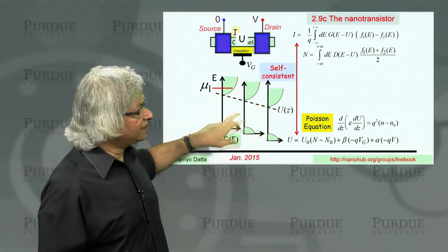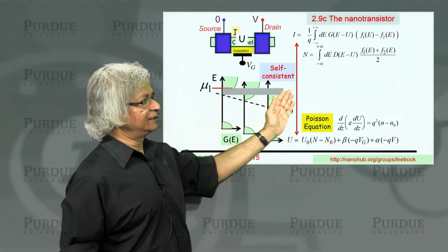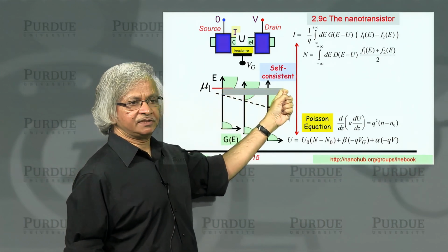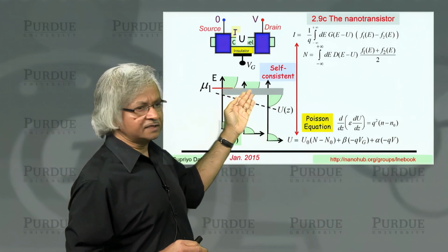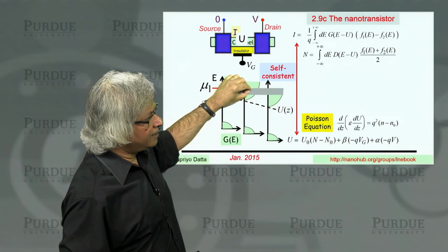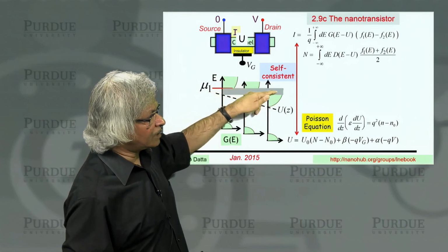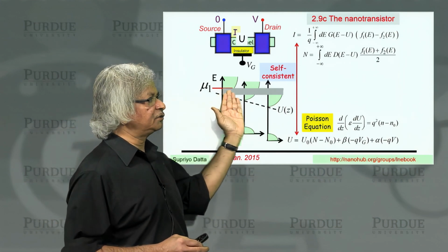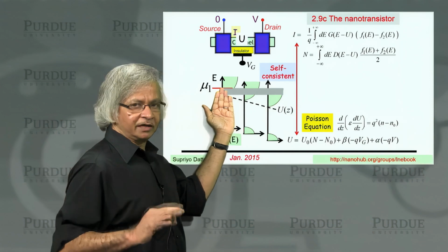Okay? Now, one thing that it misses here also is that, remember, our entire model here was based on this elastic transport, which means the assumption was that an electron coming in from here, as it goes through the channel, does not change energies. And if it's a ballistic device, that's usually a good approximation. That's fine. But on the other hand, if you have diffusive processes going on, so that electrons lose momentum in here, then there would be a lot of situations where these electrons, instead of being confined to this energy channel, would want to go down here. And once they go down, they are able to carry on to the drain. So the point I'm trying to make is, if you have a model which allows electrons only to travel in the channel they started in energy, then you'll tend to calculate a much lower current than what you actually get.